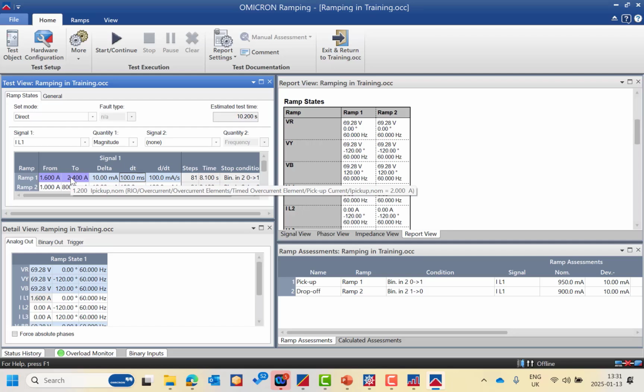So if you have this kind of application, you can also use the automated solution using the General Test module, but just use the Link to XRIO feature. For the dedicated modules, don't worry, they will be automatically linked to the RIO file and to your parameter setting. But for the general modules like Quick CMC, State Sequencer, Ramping, Pulse Ramping, you can link to XRIO using this feature. So it will be automatically adapted.